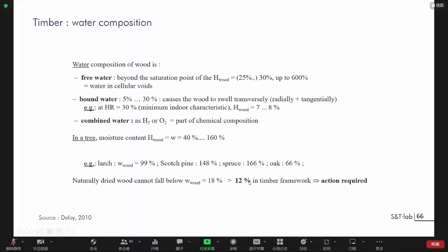So you have to move this water outside of timber, since indeed there is a connection between water and the fungi and also the beetles that will be attacking timber. The third kind of water, this free water, is just the water that is running in the tubes of timber. As soon as you cut the timber and put it vertically, you will see this water just flowing down from the tubes. And so it can be eliminated very easily.